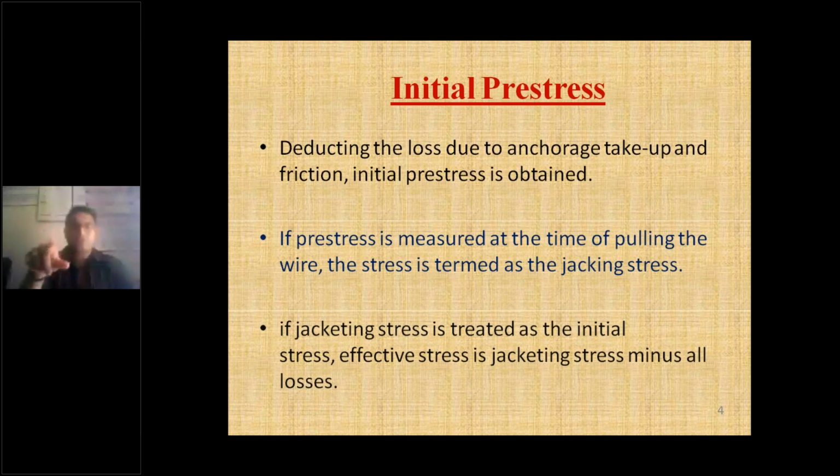So where you are going to measure the stress which we are applying in terms of pre-stressing, you are going to measure that pulling force. Okay, you are going to measure it in the jacking system. In the stress jacking system, you can measure the force, how much you are applying to pull the strands. So that jacking stress is going to be treated as the initial stress.